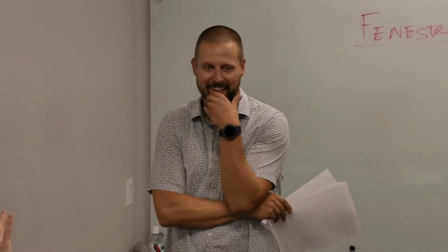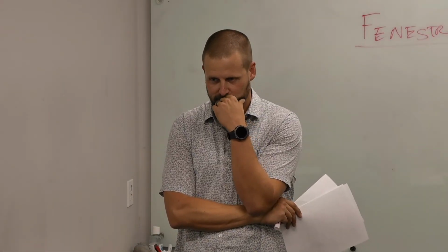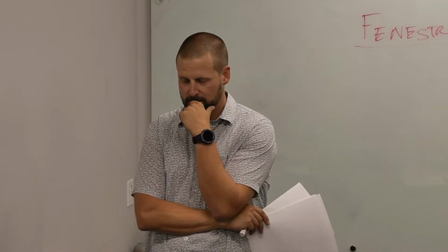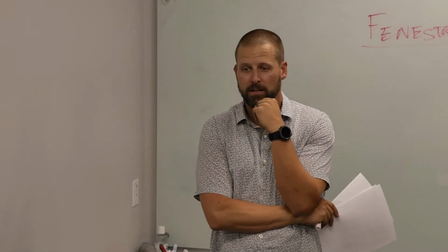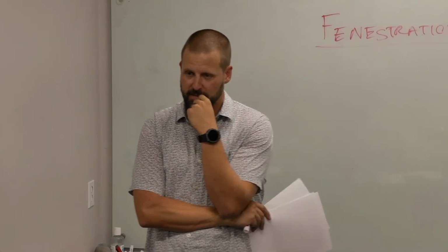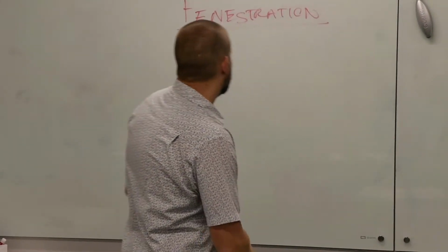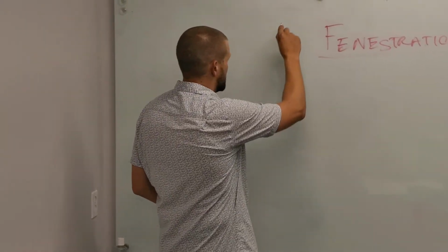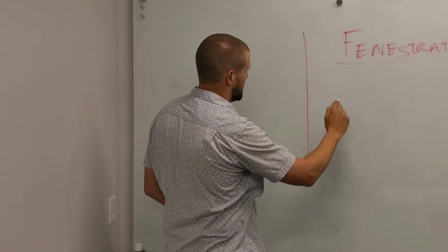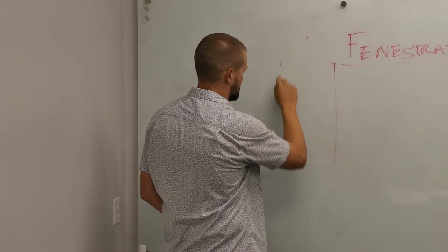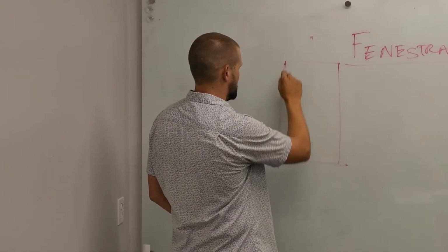Arguably, if the window's high up, could you say that the loads in a stratified space don't necessarily affect your actual occupied zone? Yep. So from a load standpoint, you could use that. If you have a high space, we'll make a rectangle, because rectangles are the best.